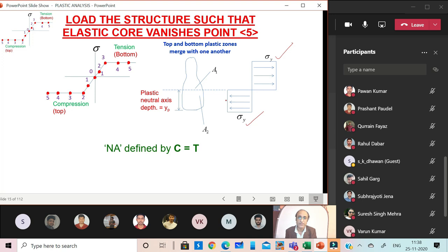But we assume that the section still has the capability to resist any kind of rupture, so the plastic moment capacity is there, and the conditions are such that the section can develop it. It does not fail prematurely by some other reason like buckling or by rupture of the material itself. So we assume that the material itself is very ductile.